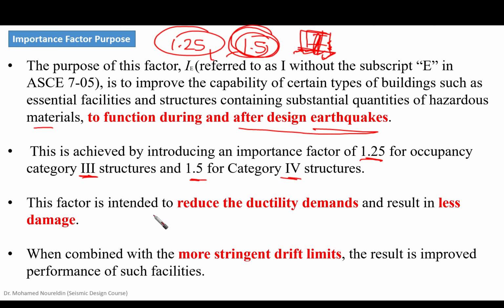This factor is intended to what? Reduce the ductility demand. What is the meaning of this? If we look at the structure itself, this is the common pushover curve of the structure. If we multiply the design force by IE, which is 1.5, for example, we're going to find that the structure is going to behave something similar to this.